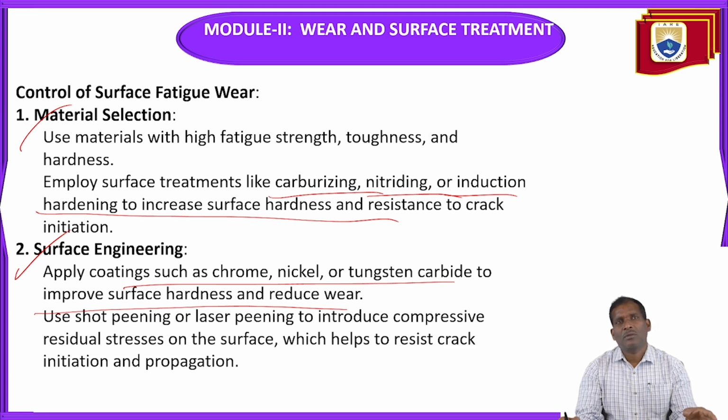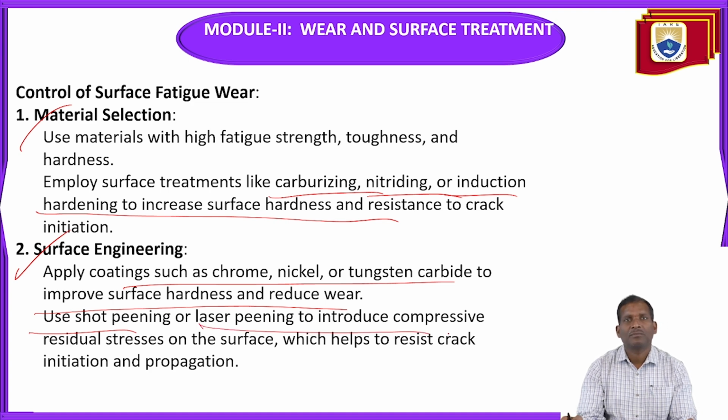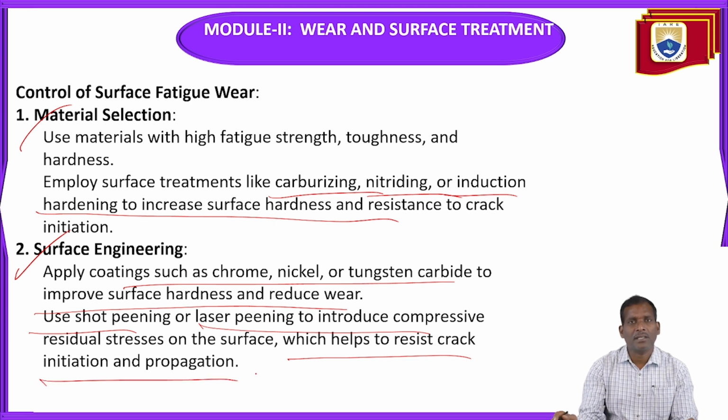So by applying the coatings, you can control the surface fatigue wear, because the surface hardness will be improved. Use shot peening or laser peening to introduce compressive residual stresses on the surface, which helps to resist crack initiation and propagation.